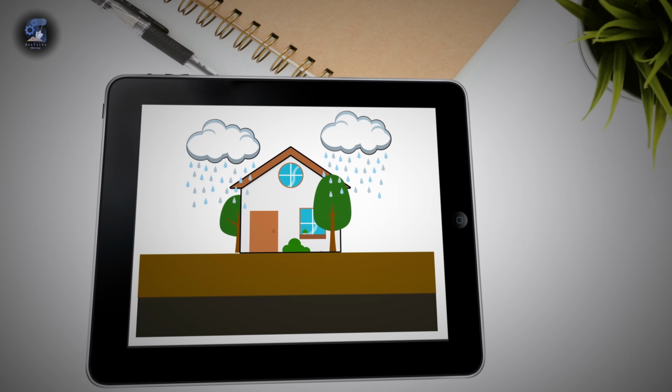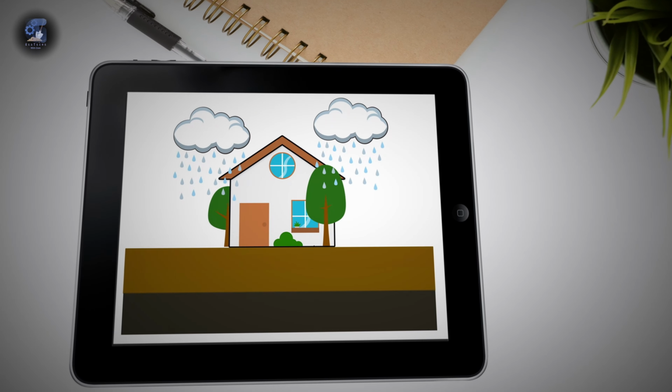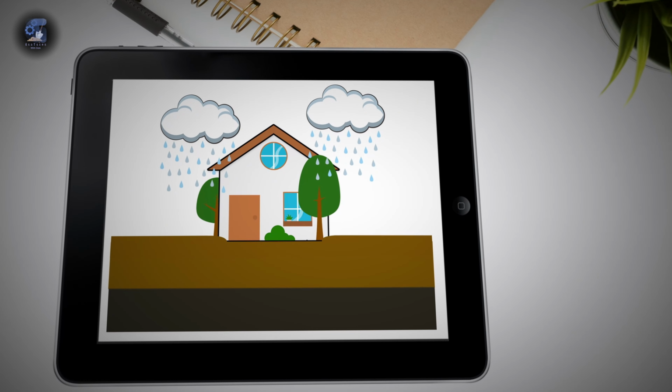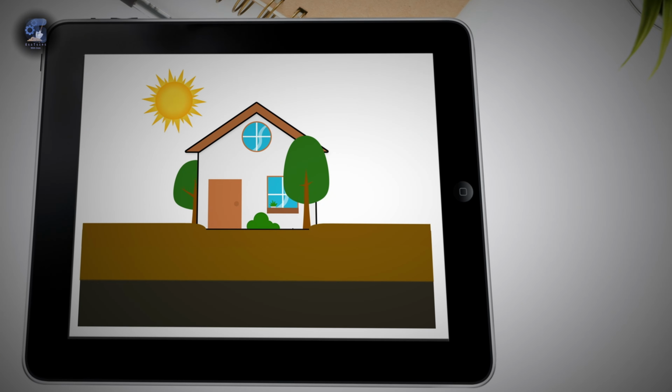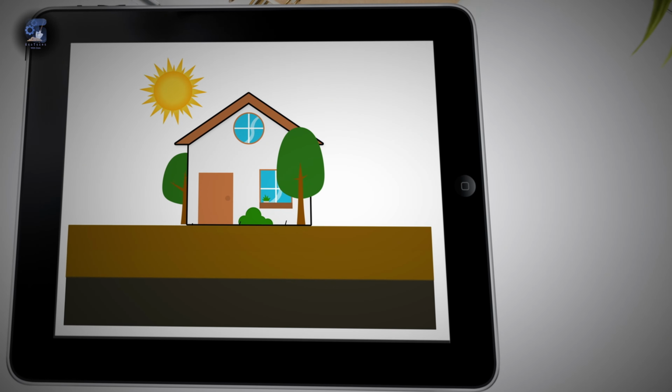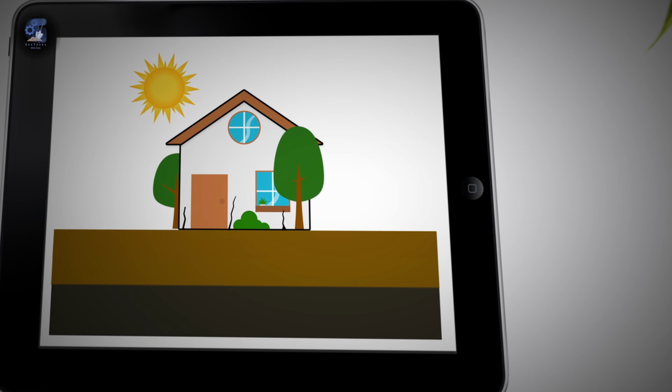So, what makes reactive clays so problematic? The main issue is their ability to expand and contract due to their microscopic structure. This movement can cause foundations to shift, walls to crack, floors to become uneven, and even plumbing systems to break. During wet seasons, for example, areas around the edges of the buildings are exposed to more moisture, causing them to expand first and create an uneven displacement. The reverse happens during the dry seasons, creating stresses on the building and utilities, leading to cracks and breaks.